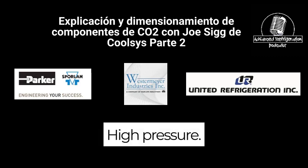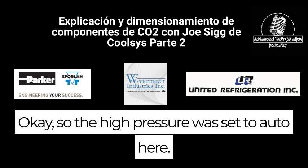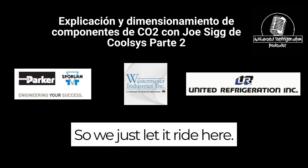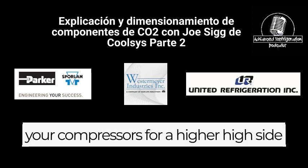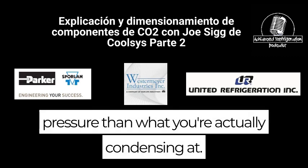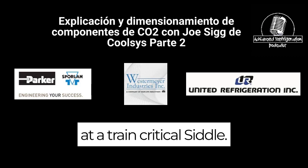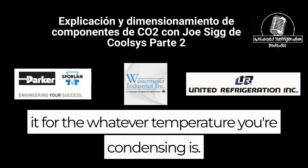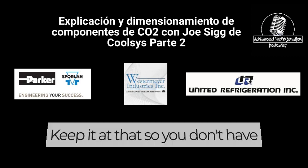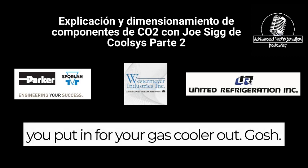That's the intermediate pressure. I'm looking at the high pressure, which was set to auto here, so we just let it ride. If you're selecting this, you can select your compressors for a higher side pressure than what you're actually condensing at, if you're trying to look at a transcritical side. In this case, we selected auto, so it's going to select for whatever temperature you're condensing at. Keep it at that, so you don't have to worry about it. It changes based upon whatever you put in for your gas cooler outlet.